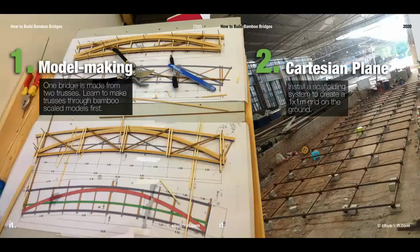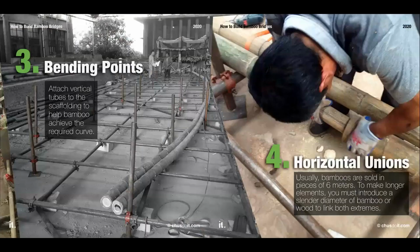Second, install a Cartesian plane to create a grid to translate exact measures from small scale to real size scale. The Cartesian plane can be made out of metallic scaffolding because it is easy and fast to install and uninstall. Number 3. Attach vertical tubes to the scaffolding to help bamboo to bend according to the required curve.